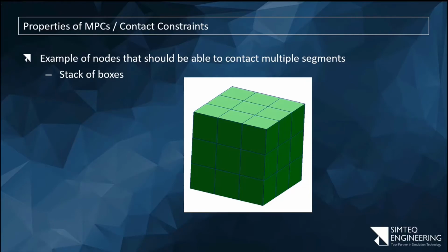Now, just bear in mind that in a finite element model, we're transferring loads purely at nodes. If I actually apply a load at a face, it's converted to forces at nodes. But when we solve F equals KU, force is stiffness times displacement, that's displacements at nodes. There are no forces at element faces or anything. Everything has to happen at nodes. So again, the algorithm will in the background have to translate between this dual concept of faces and nodes, but that's its problem.